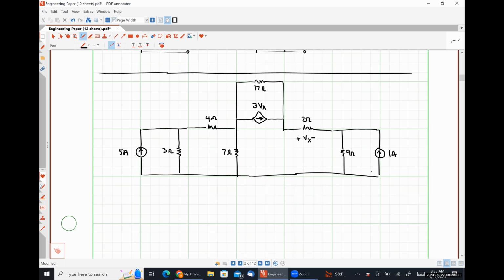So within a few steps, we are actually going to be able to transform this circuit using source transformations into a single loop circuit that we could have analyzed on the third day of class. So let's identify some things. Do we have any practical voltage sources in this circuit? The answer is obviously no, because there are no voltage sources at all. How many practical current sources do I have? 3. Nothing stopping me from treating that dependent source in parallel with a resistor as a practical current source as well, right? So I have 3 different things that I can transform here, okay?